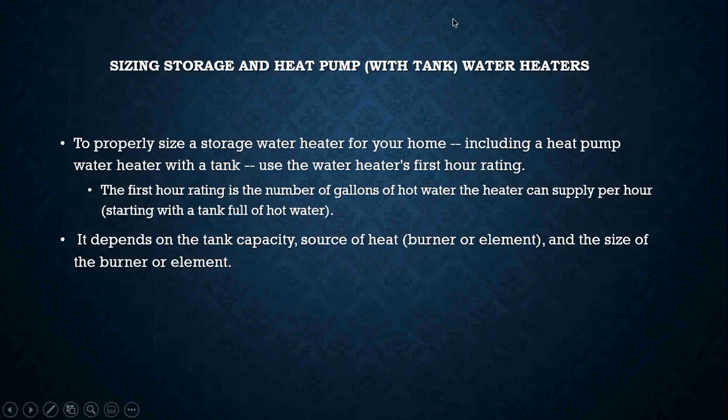So, sizing storage and heat pump water heaters. To properly size a storage water heater for your home, including a heat pump water heater with a tank, use the water heater's first hour rating. The first hour rating is the number of gallons of hot water the heater can supply per hour, starting with a tank full of hot water.